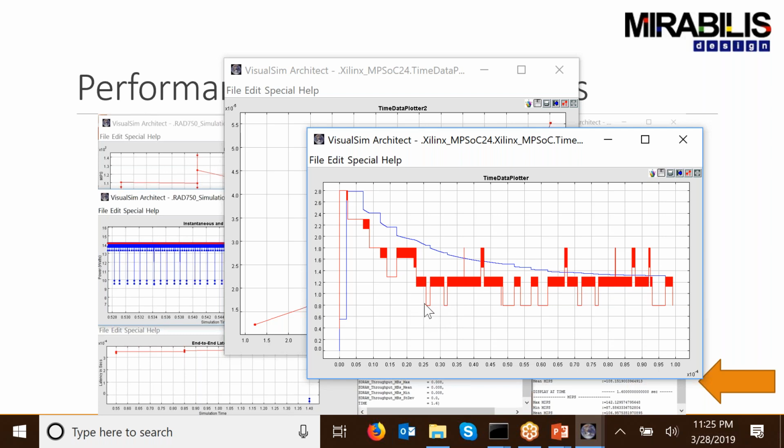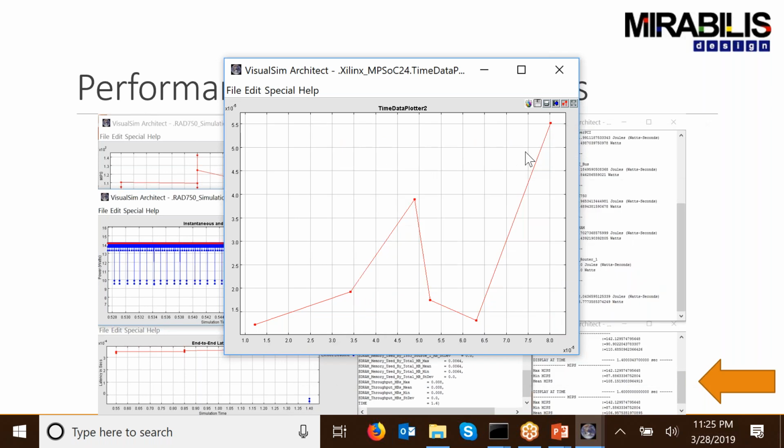This is not just for one component within the FPGA, but this includes all the buses, the memories, the processors, and the programmable logic. So you can actually cover the power consumption for all of those subsystems to give you a gauge right up front as to what your performance and power consumption trade-offs are in your particular design.